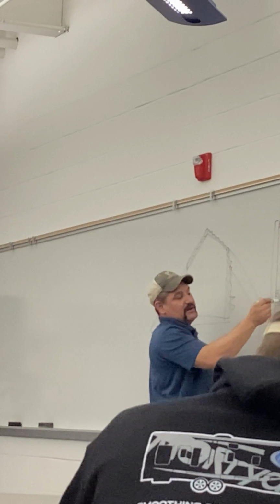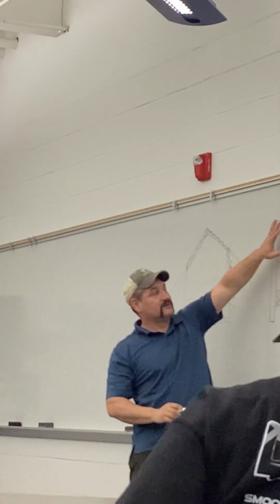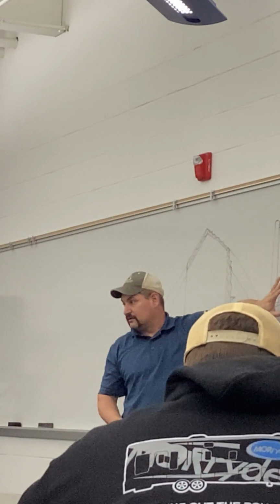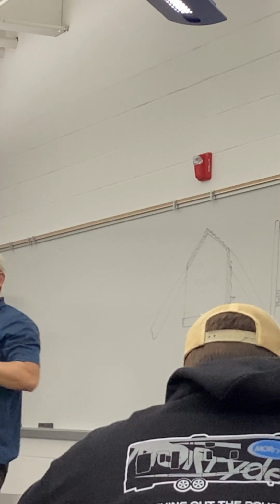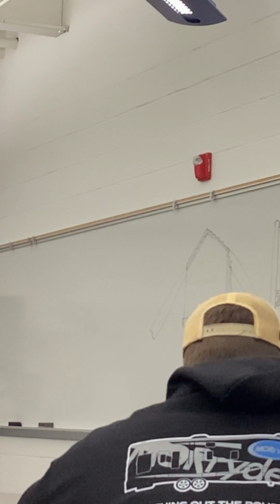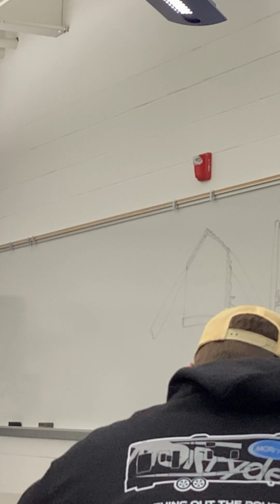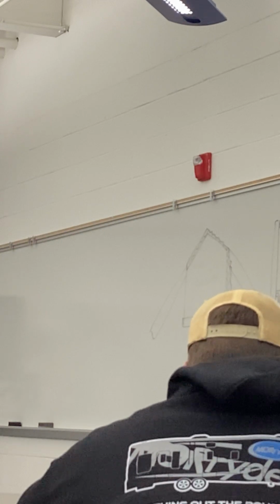Just by leaving this gap and that gap and a gap around the outlet, you lose 40 to 60% of the efficiency of the whole thing. Not just right here, of the whole thing. So the installation of the insulation is difficult. It's difficult to predict, if you don't have good insulation, how well it's going to perform.